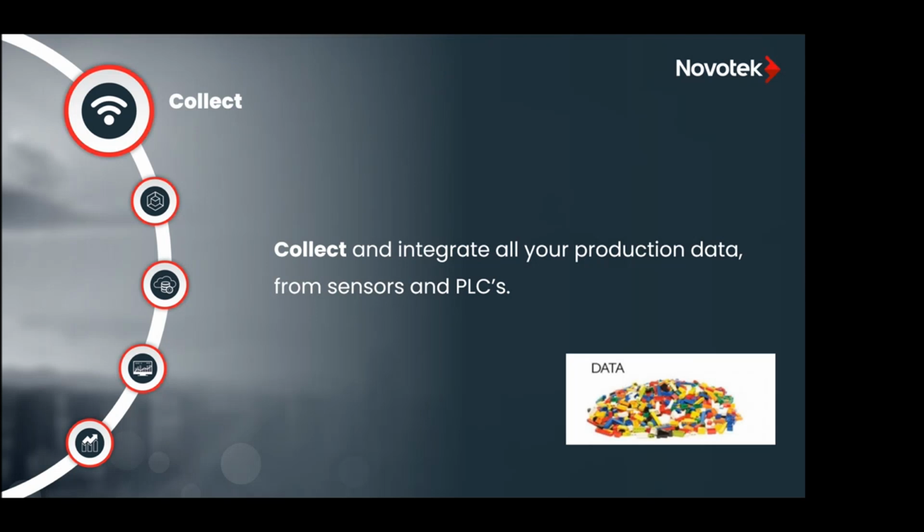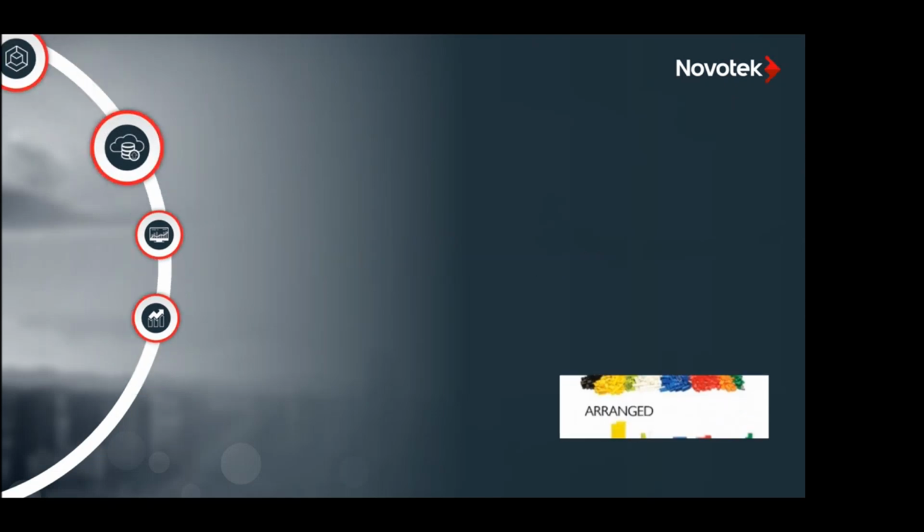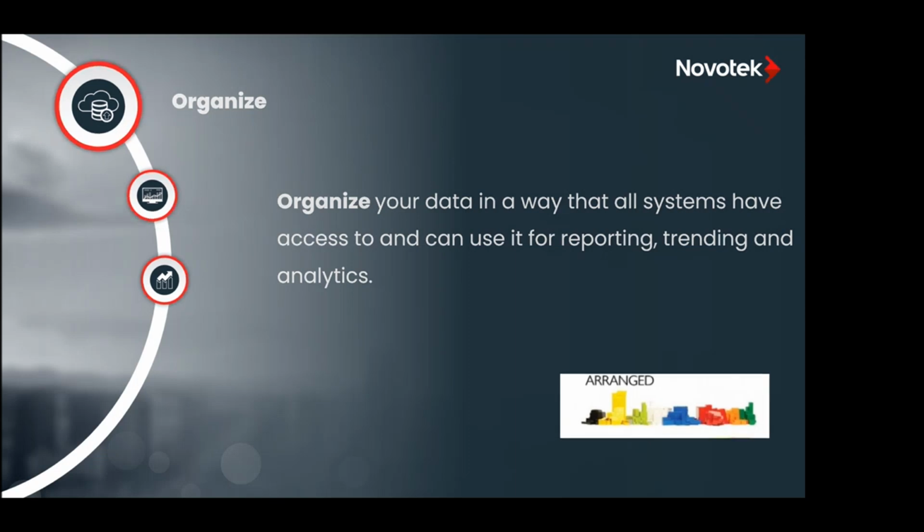We collect and integrate production data from sensors and PLCs. Next, we sort and standardize the production data. Think of different engineering units, different sample frequencies. It all needs to be synchronized, different data sources, to make it useful and comparable. Then we organize the data in such a way that other systems can easily have access to it for the purpose of reporting, trending, and analytics.